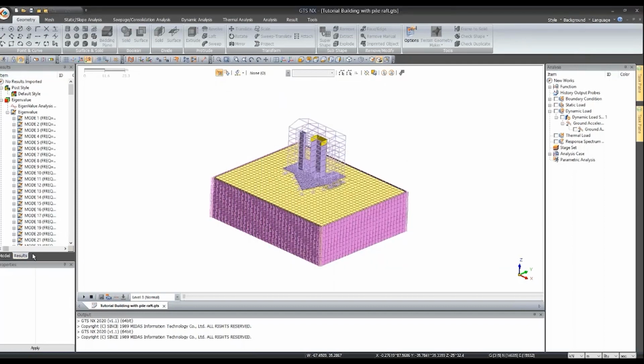So I'm interested in finding accelerations at the bottom node, on the ground surface, and at the top of the building. Sorry, so just go for absolute maximum. I'm interested in accelerations at first. So let's consider Tx acceleration, since I applied a load in the x direction.